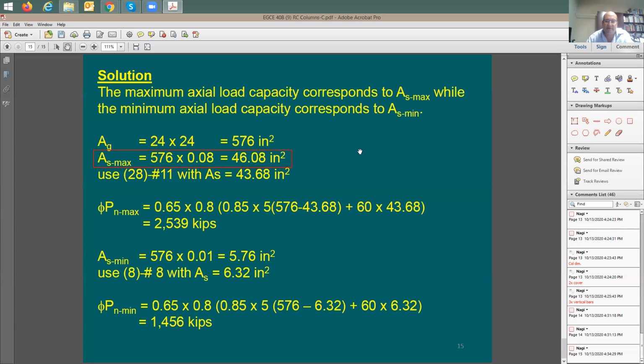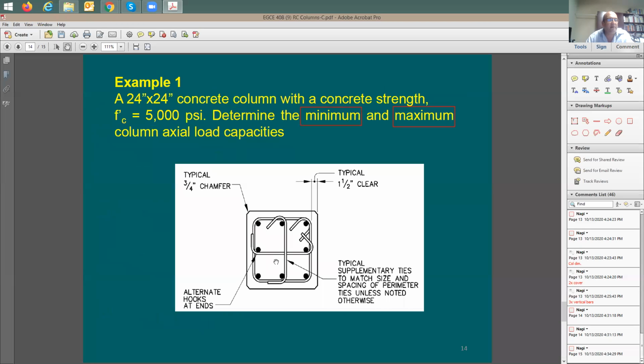Wow, this is a lot. How can I place them in there? Now, at this point, you don't have the experience, but you know it's going to be a multiple of this 8. But also, you need to know that when you lay out the reinforcement, don't forget that you're going to have this symmetry about both of these axes, which means your number of rebars got to be 4 or 8 or 12 or 16. How about 18? Can I put 18 rebars in this column?